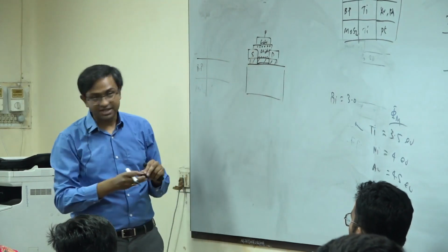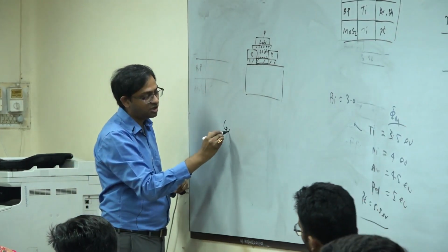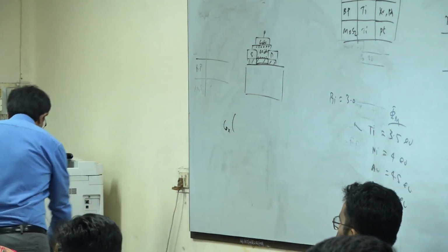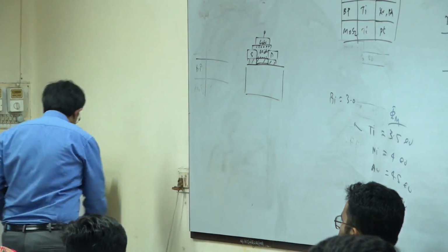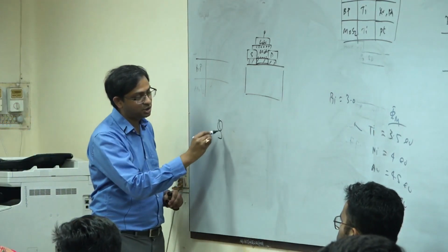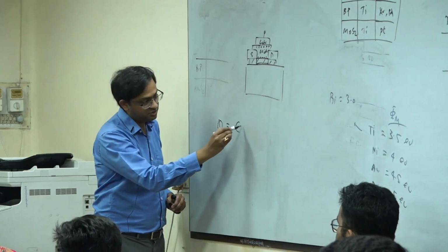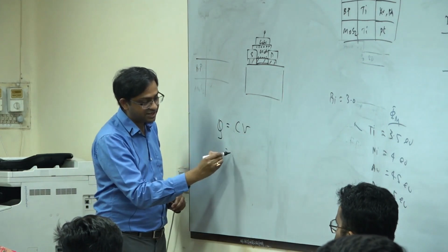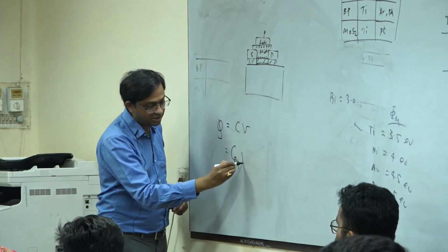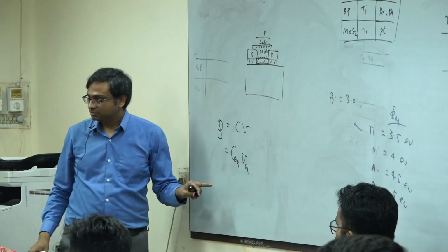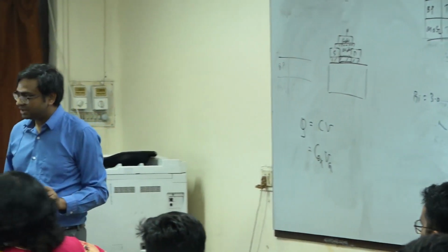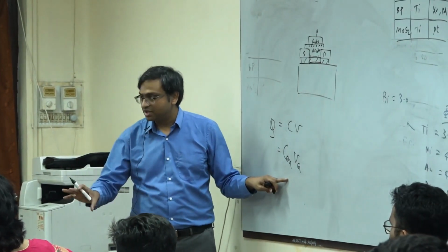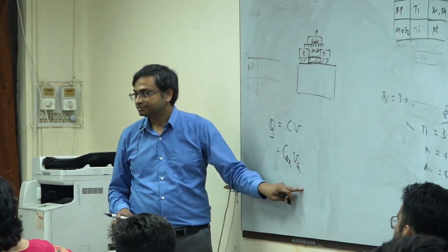And the amount of charge I can produce is Cox times Vg. Let's put it very simply, right? Because you remember, what is the amount of charge that a capacitor holds? Q is equal to C times V, right? So in this case, whatever channel charge I can provide will be Cox times Vg. So far so good, right? So the maximum charge I can deplete, take away, or put into the channel is this amount, okay?